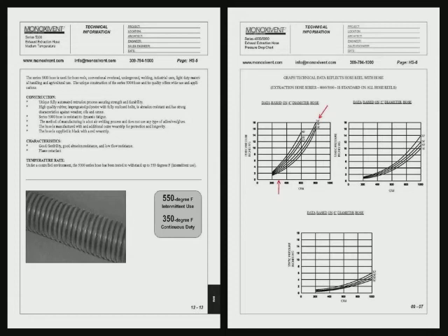You can see from the performance chart on the right, in this case 24 feet of hose, 4-inch diameter at 300 CFM is roughly 3 inches of static pressure. Keep in mind that that particular number is going to be a little bit of a moving target, because as the hose is wound and unwound onto the hose reel, that number can change. It can change quite a bit. Having the hose completely wound up on it and taking a reading versus having the hose pulled perfectly straight off of it and taking a reading are two entirely different numbers for static pressure. In this case, these numbers are based on roughly half the hose off the reel, so it's going to be close to where you're going to see them actually using the hose in the field on a vehicle. So with that, we got roughly 3 inches of pressure loss in the hose.